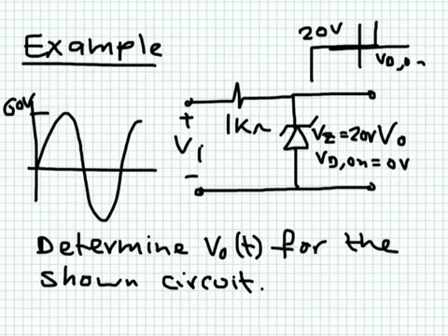So once you apply negative voltage, so this terminal is more positive than this one, the diode will turn on, allowing current to go through, meaning that the voltage across this diode will be equal to 0, and the output voltage is equal to 0. Now, when we apply a positive voltage, so you make this terminal more positive than this terminal, this diode will be reverse biased.